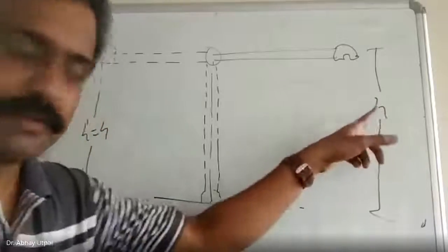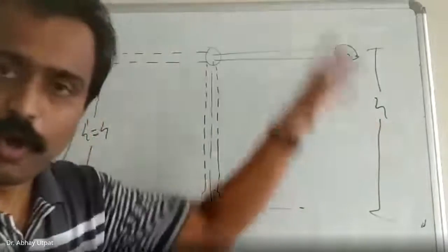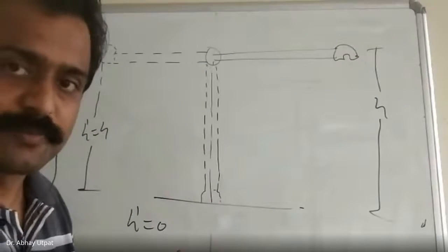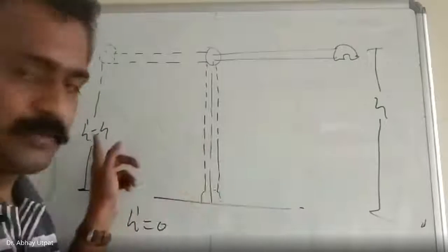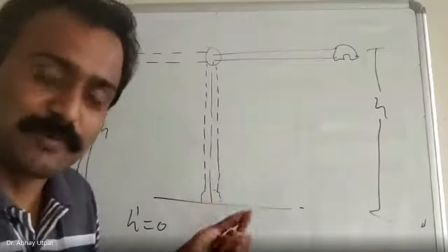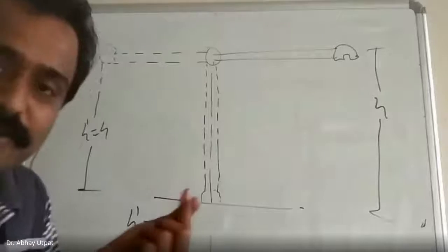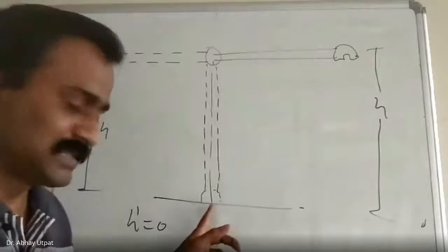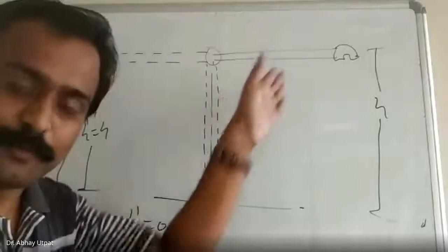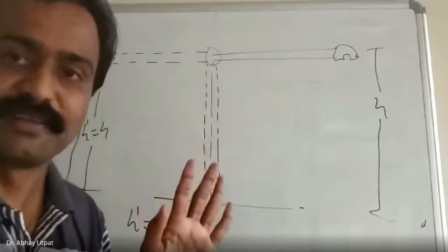In case number 1, toughness is maximum, all energy is absorbed. And in case number 2, no energy is absorbed. And if H is exactly equal to H dash, there is no specimen. If some specimen were there, at least 1% would be absorbed by it for breaking. As there is no specimen, H becomes H dash. Are you getting my point? I hope you are getting it.